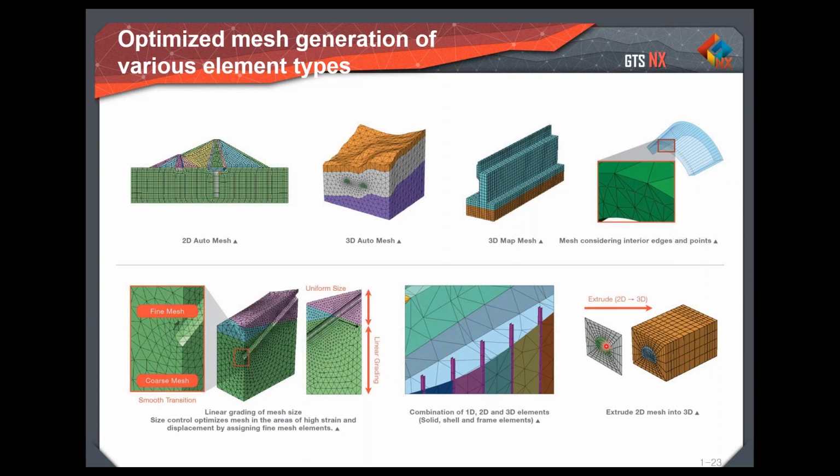And let's say we are modeling for a 2D condition, and once the 2D modeling is done, I would like to proceed for 3D. In the interim period, I want to consider my 2D modeling as a 3D modeling, apply loads, and go for analysis. So what you can do is, for the mesh that has been generated in 2D, you can extrude it into 3D, find 3D elements, and run the analysis. So that's simple. There is compatibility, and you can change from 2D to 3D at any time.